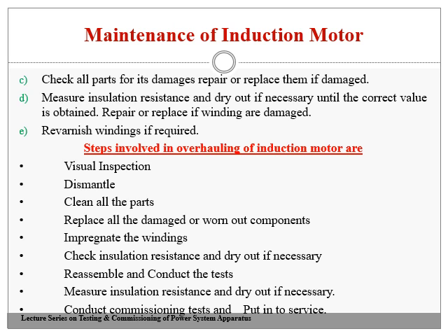Use blowers to remove all the foreign particles. Replace all the damaged or worn out components. Impregnate the windings. Check the insulation resistance and dry out if necessary.